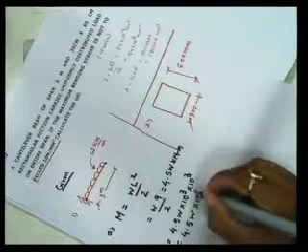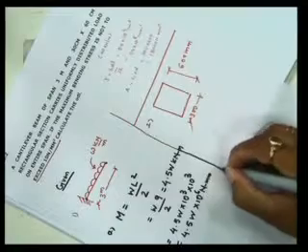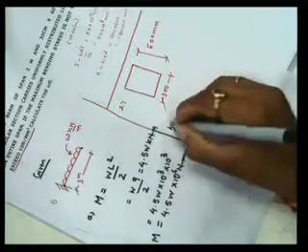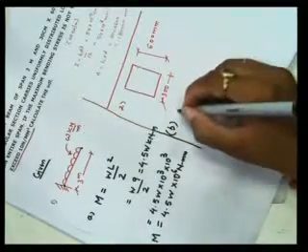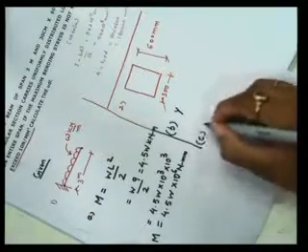10 to the power 6 Newton mm. Okay, so our first step is over, calculating the maximum value of bending moment. Right, now what is our second step? Second step is we have to calculate from the cross section the value of y and value of I.